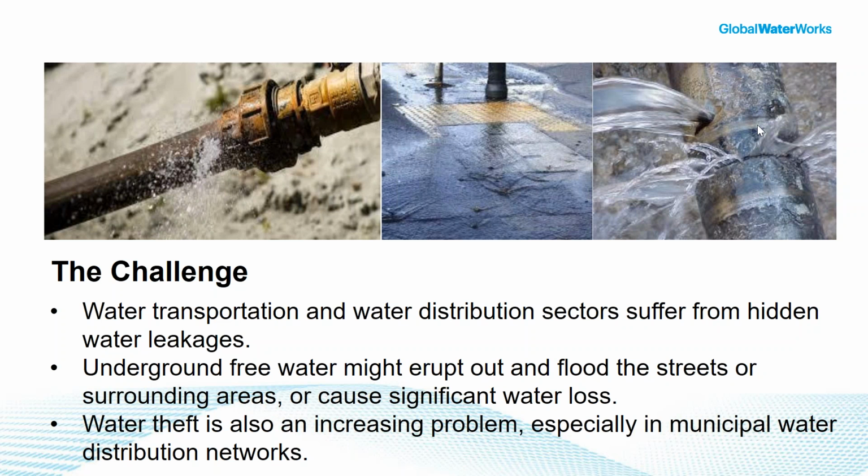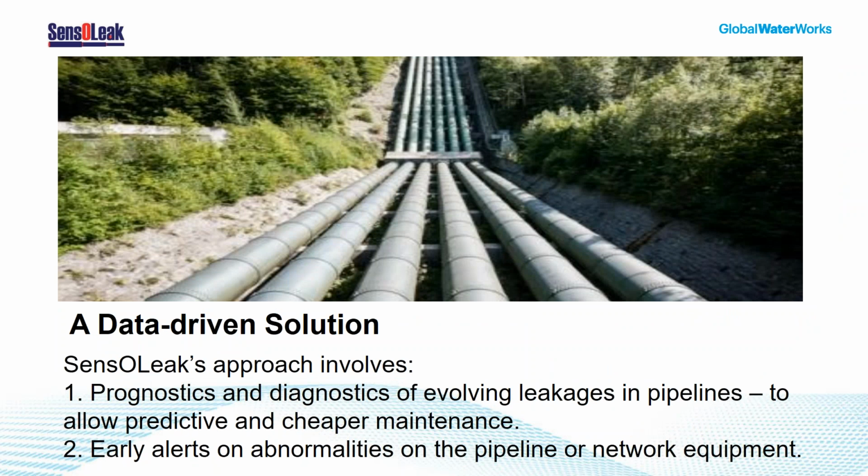We rely on the data that's transmitted from the sensors and is stored in the SCADA. What we do, we determine the normal behavior of each and every pipeline or piece of equipment that's being monitored, and then, monitoring it 24/7, our algorithm presents alerts about deviations from the norm.